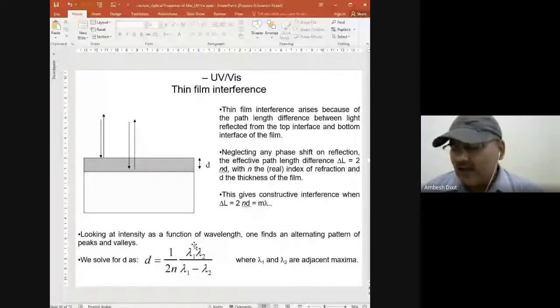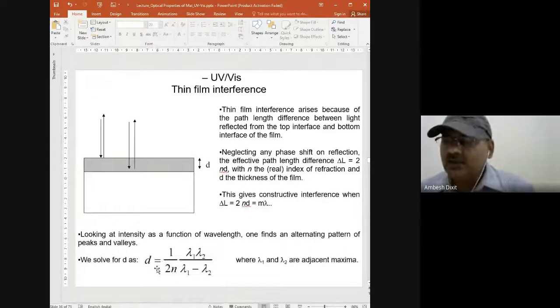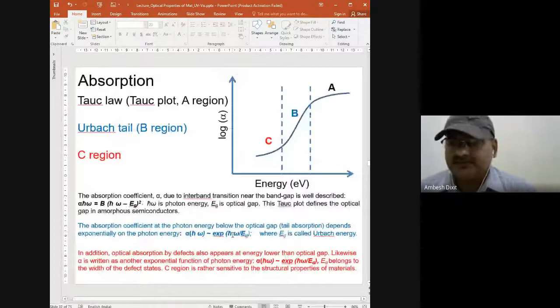You can back-plot, and the refractive index value you can take as the average value of lambda 1 and lambda 2 from the literature. You can find out what it is, and you can compare these results with the much more complicated scanning electron microscope cross-sectional images, and then you will find those are matching as well, with an error of a few nanometers. As additional information, if you have defects or even additional regions in your systems, those can also be studied.